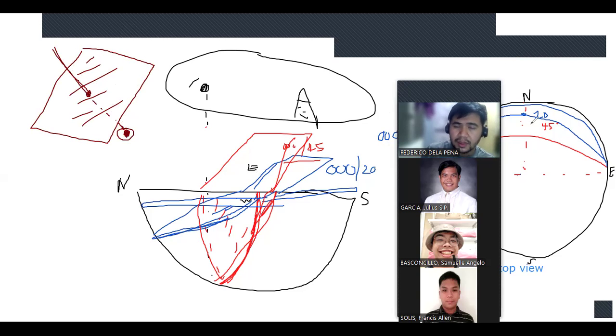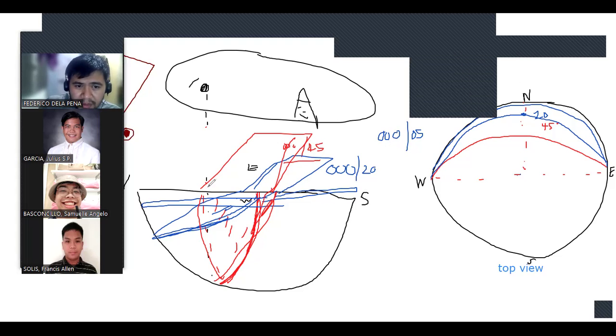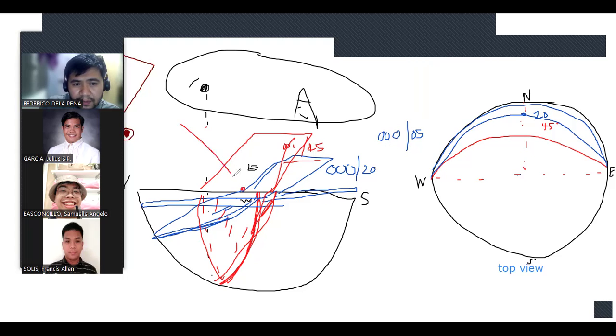Therefore, a pole plot is just a perpendicular piercing point representative of your discontinuity. If this is the plane of your discontinuity, you pierce it with a perpendicular line, or a pole, and allow it to pierce through the stereographic net, or your bowl of noodles.